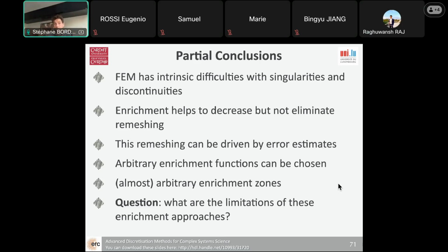Now, if you pulled a lot, you would create dislocations, you would create small fractures in the domain, and then when you let it go back, it would not return to its original length because you have residual unrecoverable deformations, which are known as plastic deformations, which you cannot avoid. So in practice, cracks initiate and grow by means of these small cracks, or even worse, dislocations in materials such as alloys, steel, aluminum, and so on.